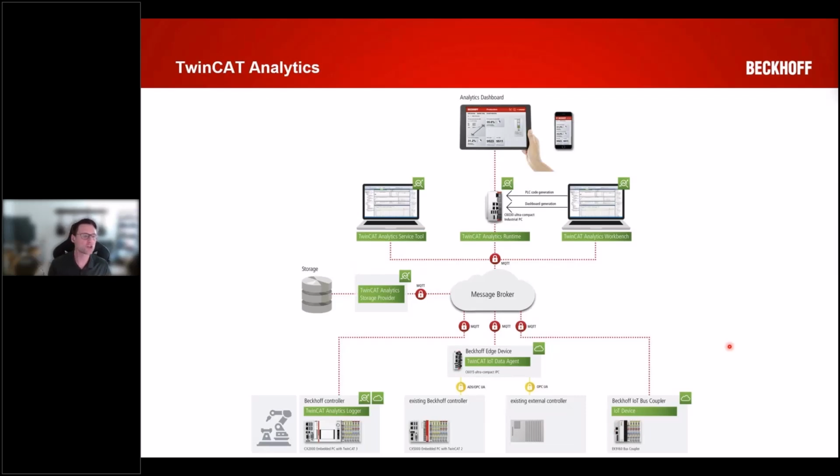Now, if you are pushing tons of data from every single device, you might need to build out an architecture that's scalable, that utilizes multiple instances of MQTT message brokers, of storage providers. And that's not uncommon at all, but they're all designed to work with multiple controllers. So if, for instance, just hypothetical, you have between 5 and 10 controllers, you could very easily realize that configuration with a single broker and a single instance of the storage provider.